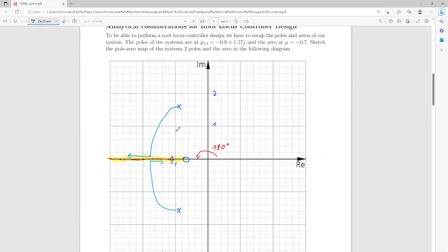But we should discuss that probably. So that means with proportional feedback, we can increase the damping here. If we assume the pitch rate is a pure velocity measurement, that would be a pure increase in damping, but actually the pitch rate is not a pure velocity feedback. It's a little bit coupled. So we will see a little bit later when we do the exact Matlab plot that we also change the eigenfrequency a little bit.